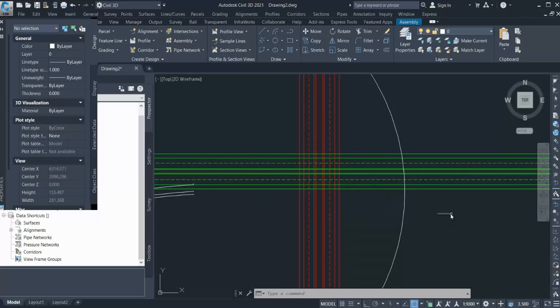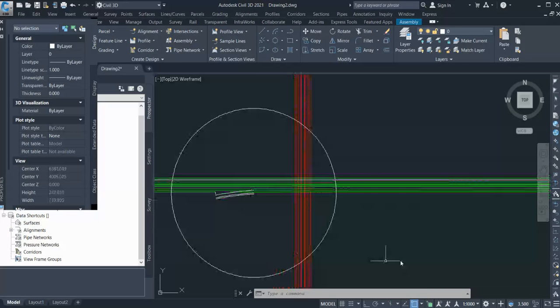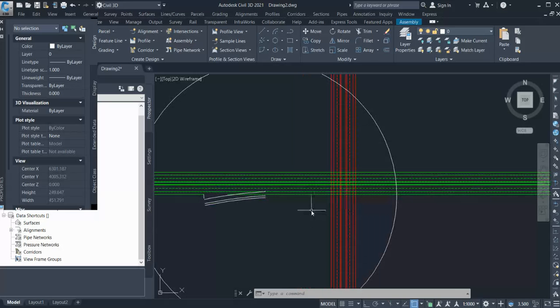But you need to make sure that you can provide a sufficient length between diverging and the merging. So one is diverging here, the other loop will come from here and attach somewhere here. You have to make sure that you have sufficient length between those two. And that depends on the traffic, what would be your weaving length. So right now we are just going with the diverge taper.